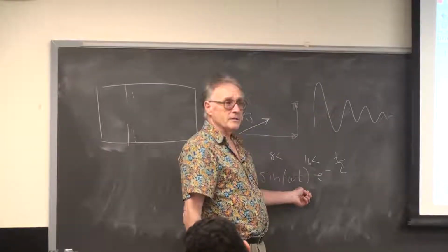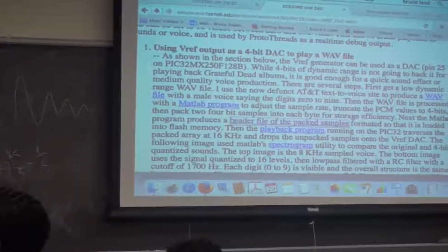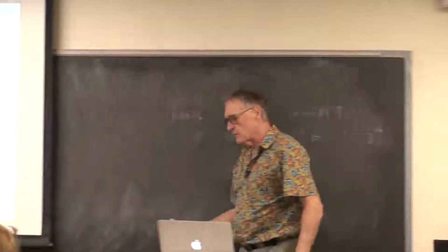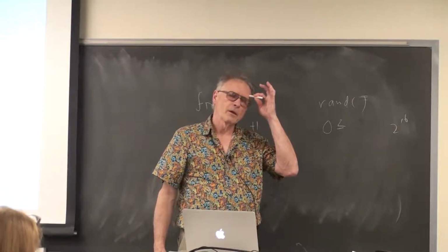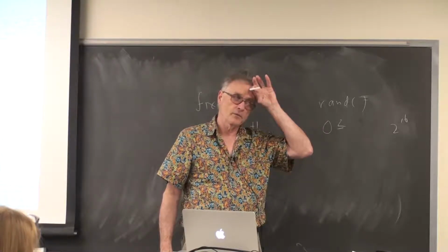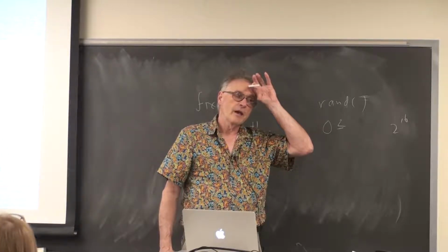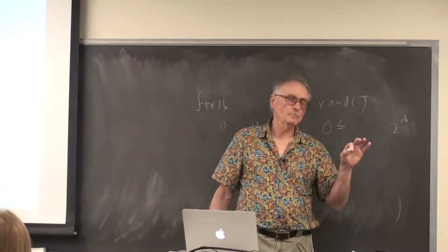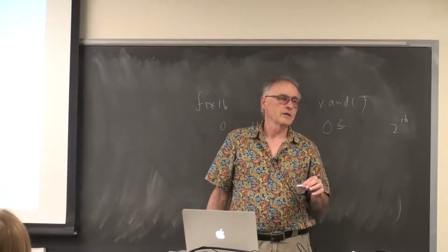You could generate that easily as an array, convert it to a header file, store it in Flash. So anything you can algorithmically describe as a mathematical function, you can immediately calculate in MATLAB and store as a header. Otherwise, you have to input it as a wave file. How do you input a wave file? You can input an arbitrary sound using audiorecorder, which is a MATLAB object that stores the audio in MATLAB as an array. You can then output that as a WAV file and input it back into my converter as a header file. Or you can modify my header generator to use audiorecorder at the input.